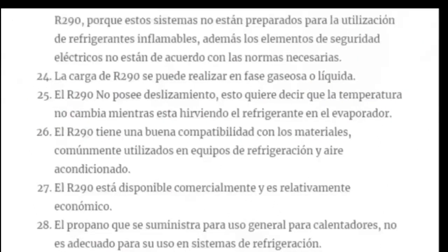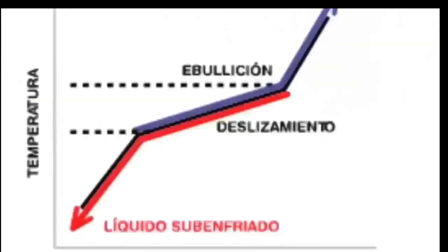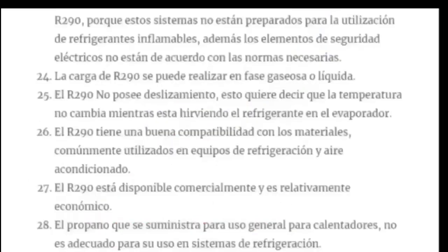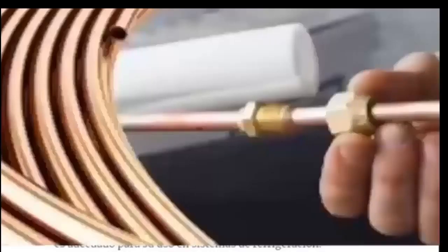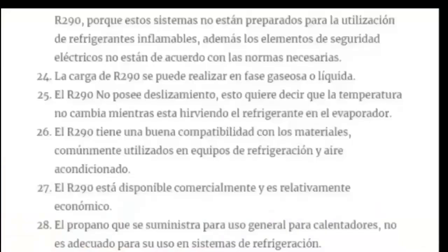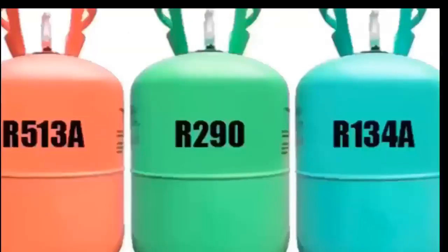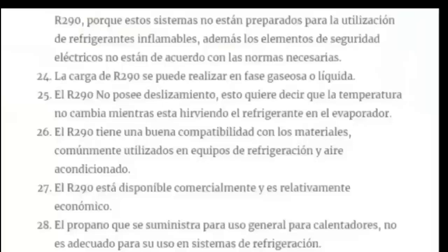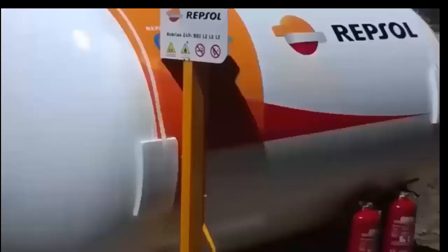25. R290 does not have slippage. This means that the temperature does not change while the refrigerant is boiling in the evaporator. 26. R290 has good compatibility with materials commonly used in refrigeration and air conditioning equipment. 27. R290 is commercially available and relatively inexpensive. 28. Propane, which is supplied for general use for heaters, is not suitable for use in refrigeration systems.